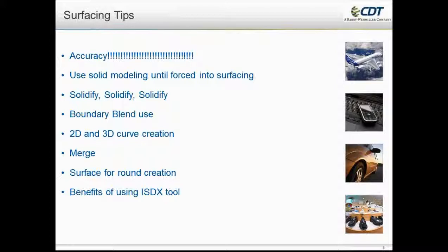If you break down your models, a lot of the time you will find that a lot of the things could be done in solids, like extrude here or revolve here, and then the details and some of the surface curvatures will be done, and should be done, in surfacing. So keep in mind that as much as possible, try to make solid models, or at least solid portions of it, until you are forced into the surfacing realm.